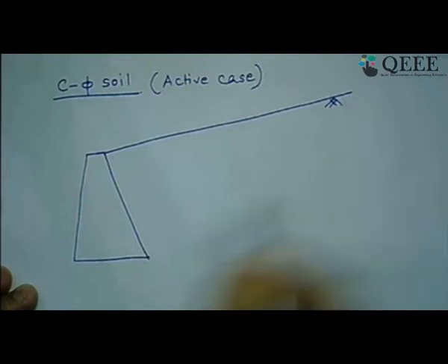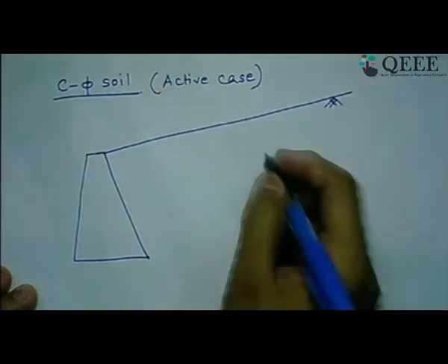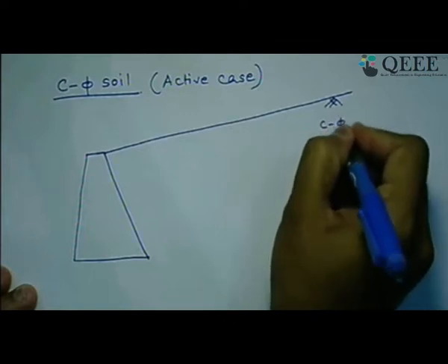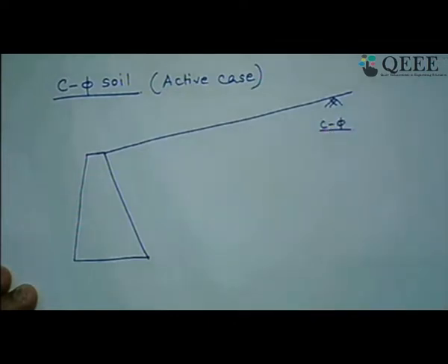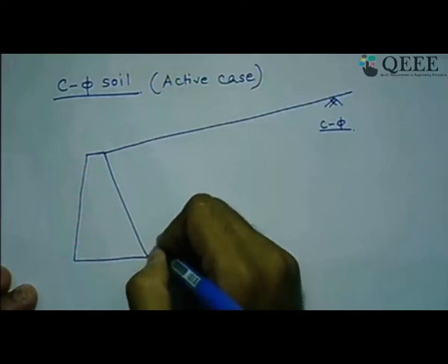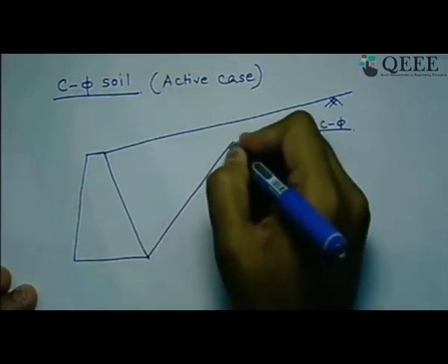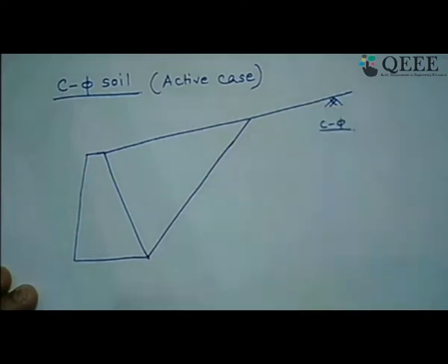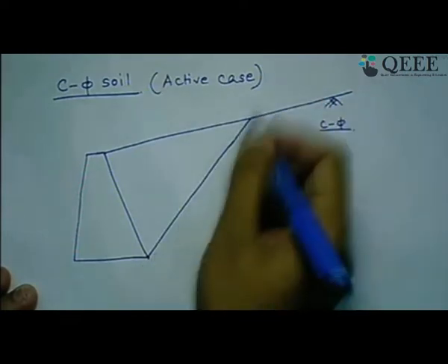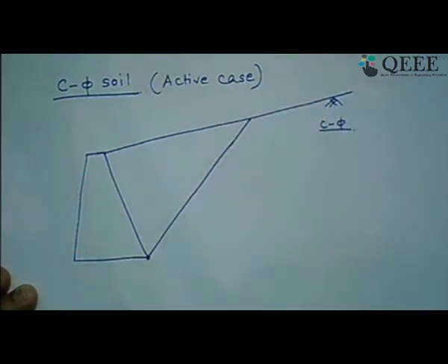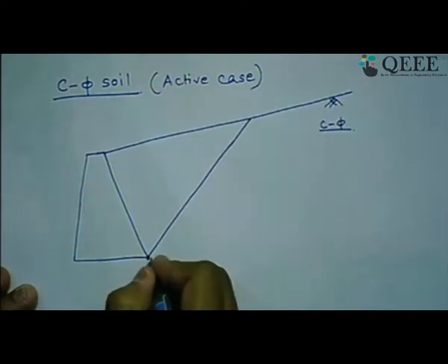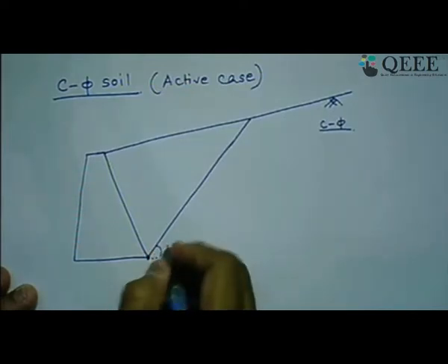This is the inclined ground surface. Now, as this backfill is a c-phi soil, what we will do here also, as per the Coulombic assumption or solution, like in Culmann's line I have drawn, the similar way you can assume the planar failure plane starting from this heel point, at let us say some failure angle of alpha.